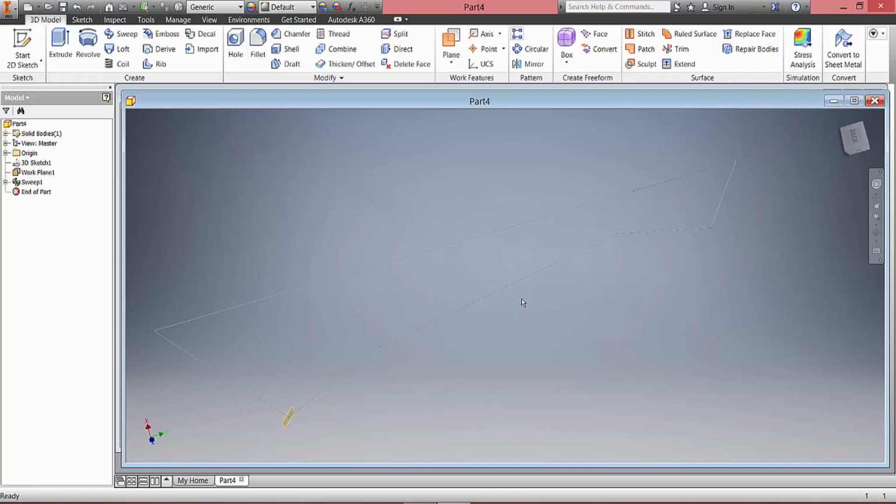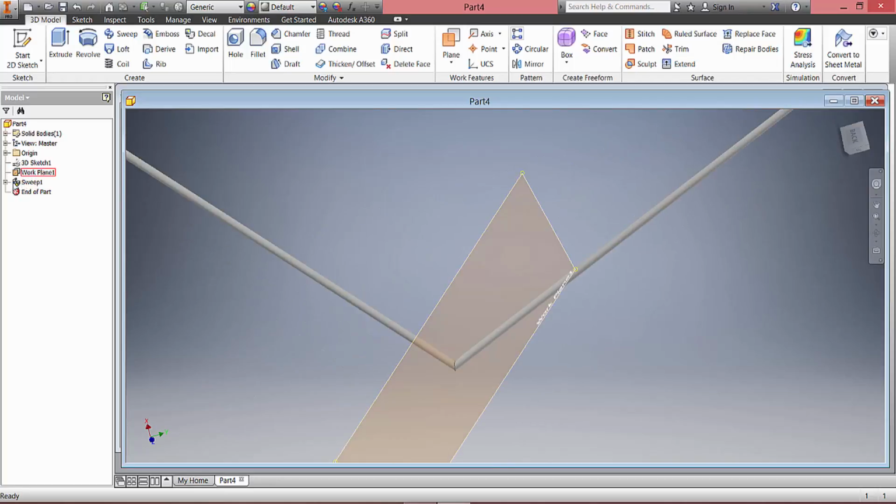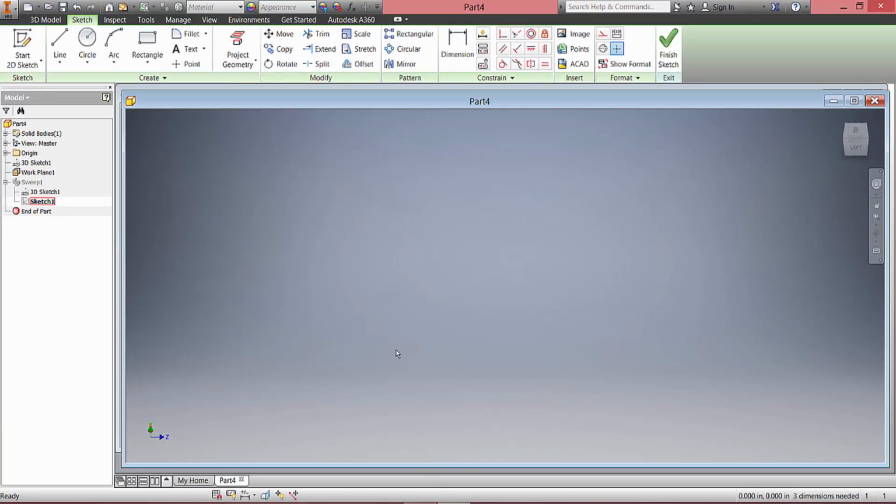Just a recommendation: if it does not sweep the entire way, it means that either your shape is too large or there's a turn in the profile that is too steep and it cannot be done. So pretty much it is saying that it can't be done.